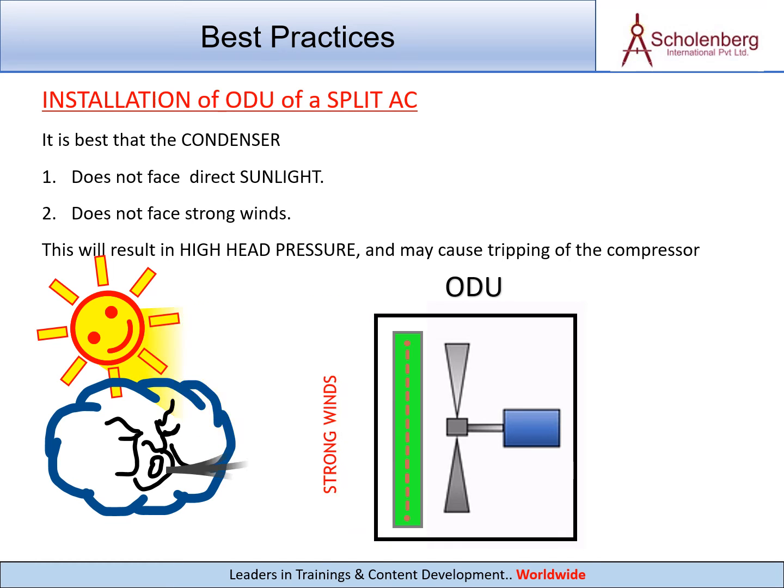Installation of ODU of a split AC. It is best that the condenser 1. Does not face direct sunlight. 2. Does not face strong winds. This will result in high head pressure, and may cause tripping of the compressor.